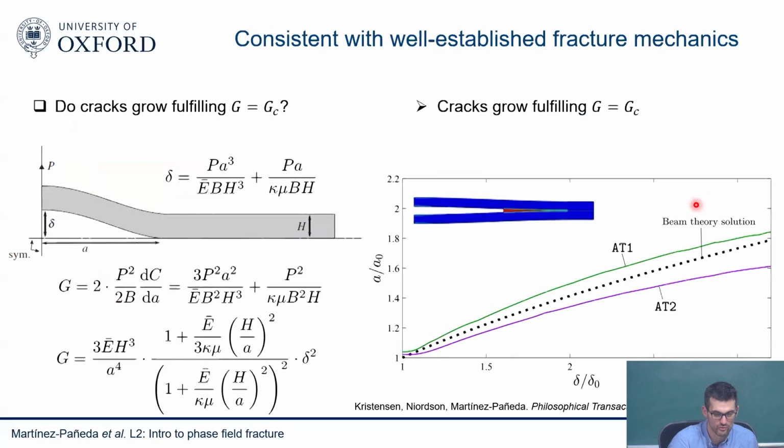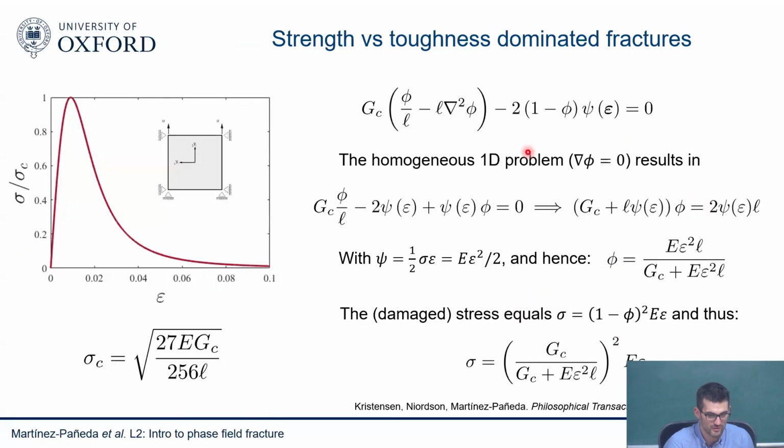That's the idea. Whenever you're solving for this equation, basically, what is G? G is an indication of the fracture driving force. So it's the energy stored in your material. It's basically a regularized version of the strain energy density you could think of. So this is what is happening here. It's all embedded within phase field. I don't need to explicitly calculate G.